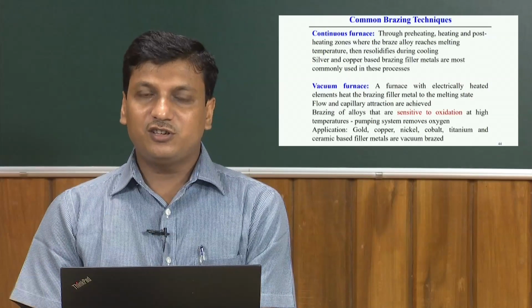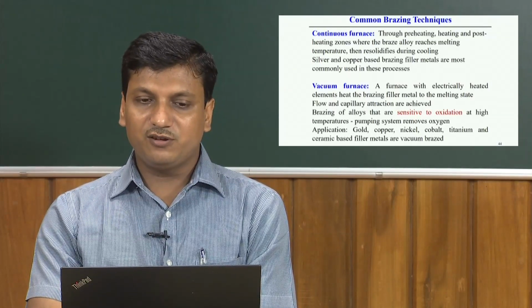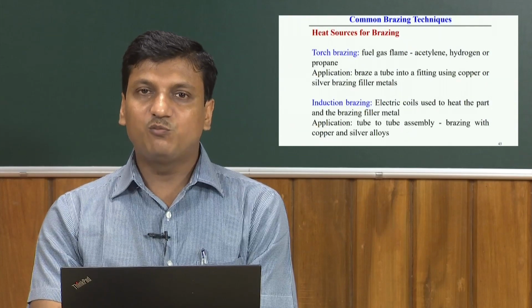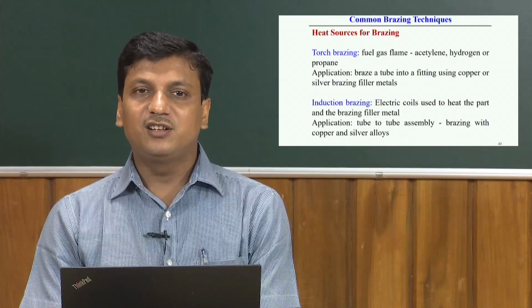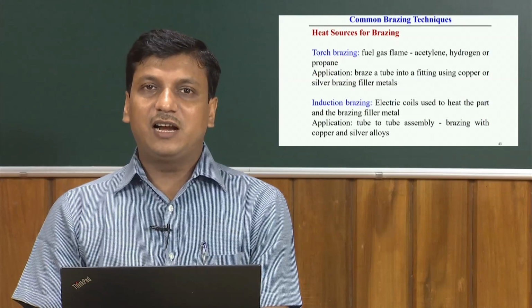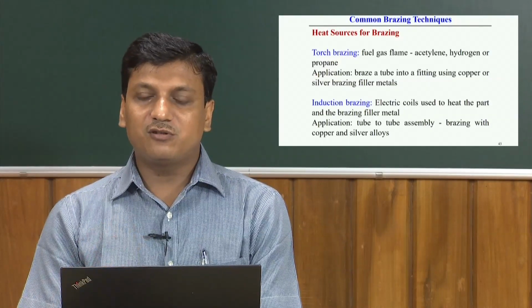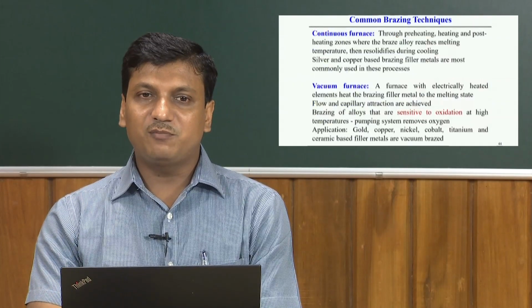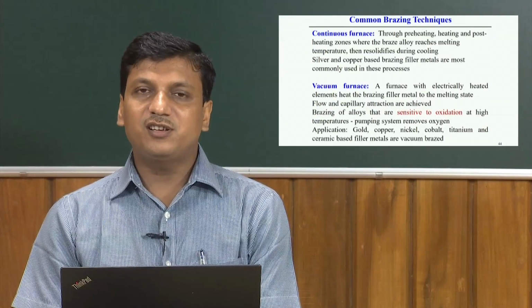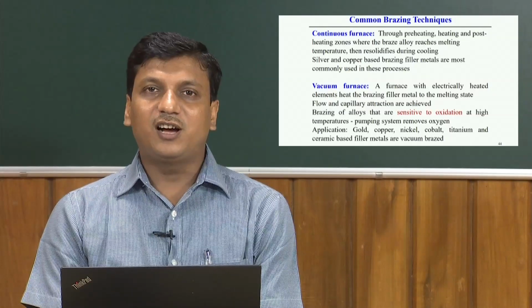So, if we consider all these different brazing techniques, the simplest application of brazing is torch brazing. Induction brazing is a more controlled approach where we can control the temperature. Then continuous furnace and vacuum furnace are also other brazing techniques.